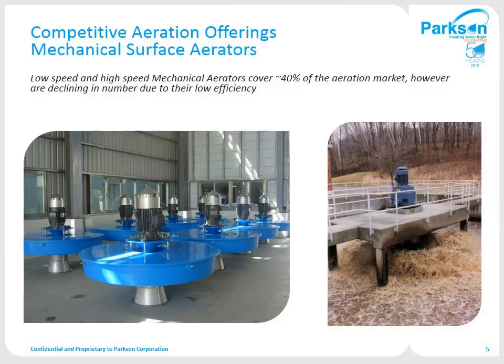Surface aerators can float on the water surface or be mounted on rigid platforms. Their most attractive feature is lower initial cost. You can see how these surface aerators splash the water into the air to transfer the oxygen. This method, however, also results in greater transmission of odors, cooling of the wastewater, and freezing problems in colder weather.